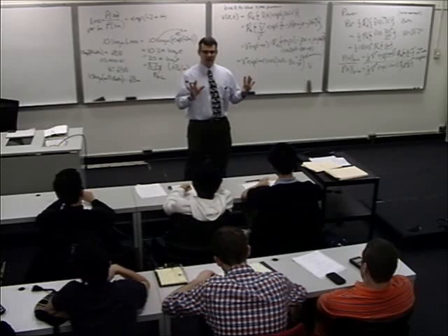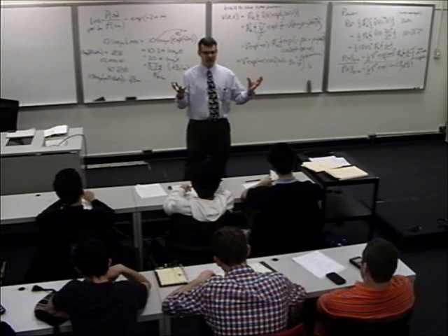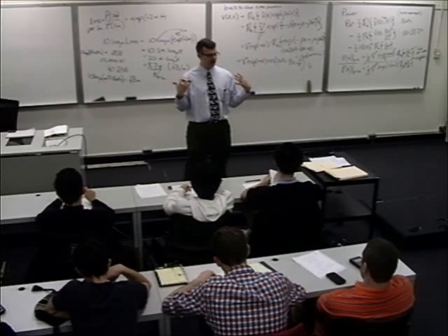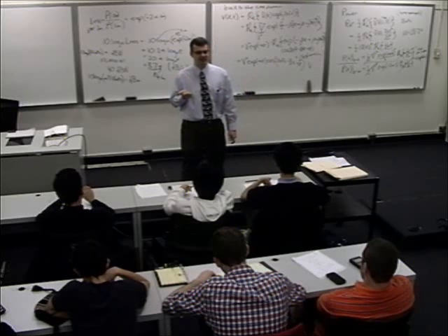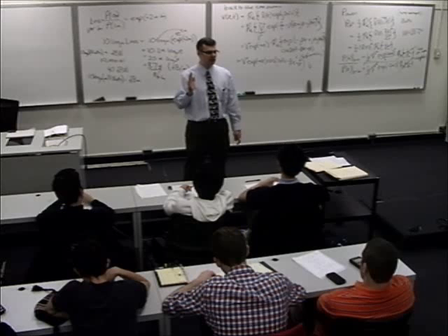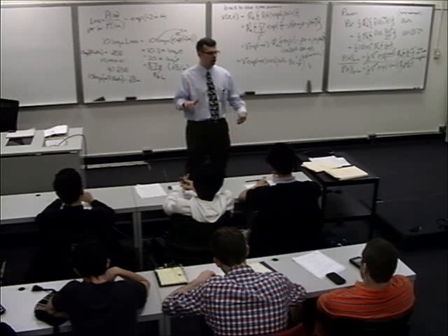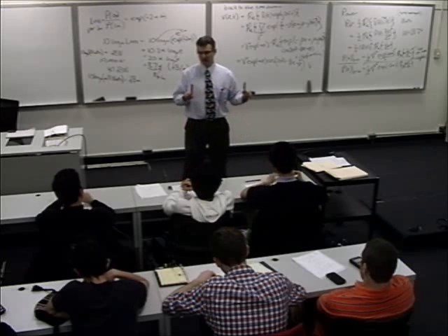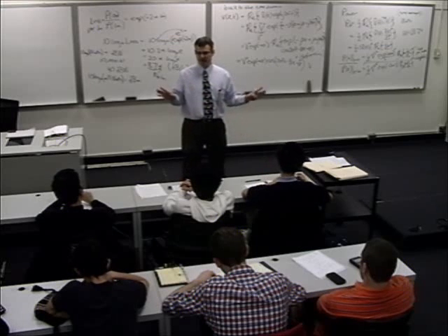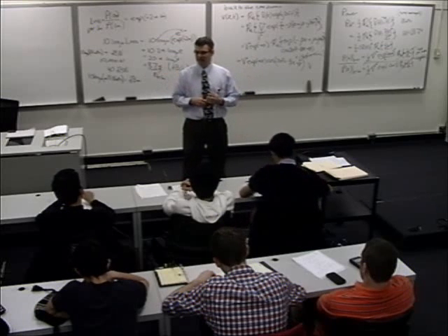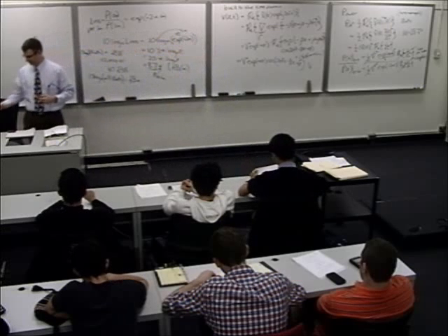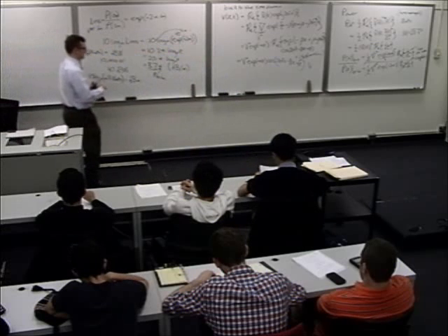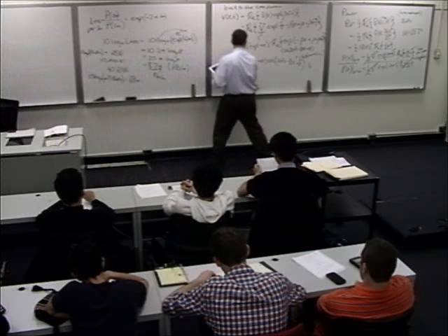So for most analysis, the equations that I put on the board here are useful simplifications that will allow you to deal with these problems. Just recognize that there is this implicit assumption that you're not losing a significant amount of power over a wavelength of distance along the transmission line. If that happens, all bets are off, and you have to go back to what we did in the first part of this lecture earlier. So let's do the low-loss approximation for transmission lines.